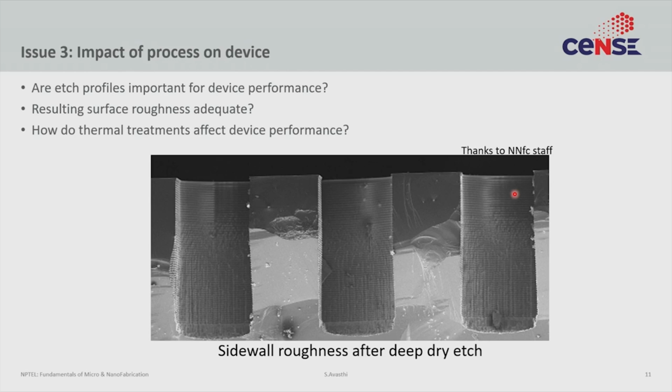If you are in the back of the line, you should probably use some sort of dry etch to clean organic contamination, or use solvents to remove organic contamination, and not an RCA recipe, right? Those are the kind of things that you have to always remember. It uses the basics that you have learned from your unit processes, for example whatever we learned in this course. You use those same concepts, but you have to remember to apply them when you are doing the process integration.